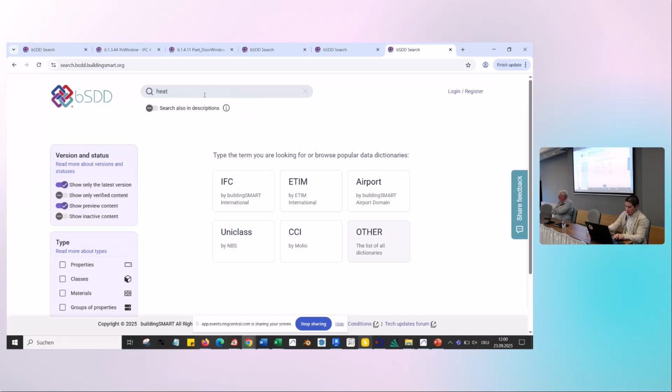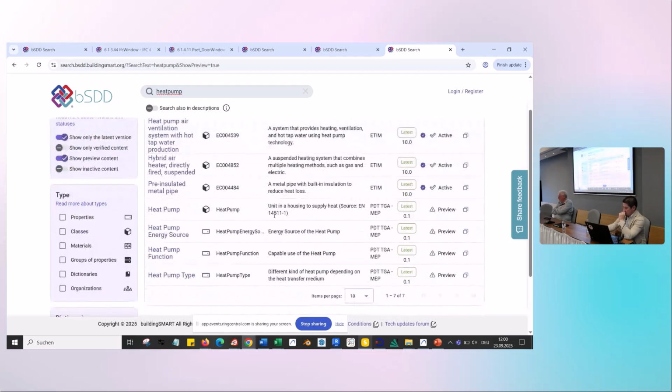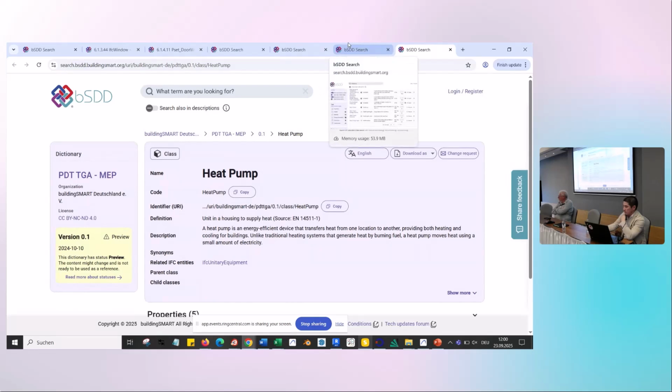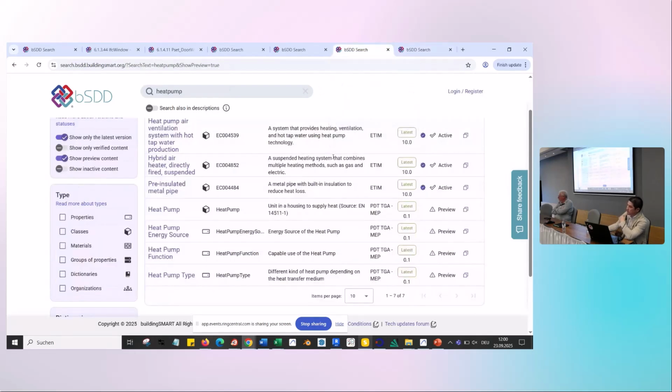And I think for the end users, because a lot of HVAC engineers are getting objects from several sources, sometimes directly from the manufacturer, exported from SolidWorks, and it's all up to the user to assign the right IFC class at the export, to do the IFC property mapping, and they are lost in this. And I think this kind of AI might help them to do exactly what you did, because you knew already what you want to find, and they often don't know what they are looking for.